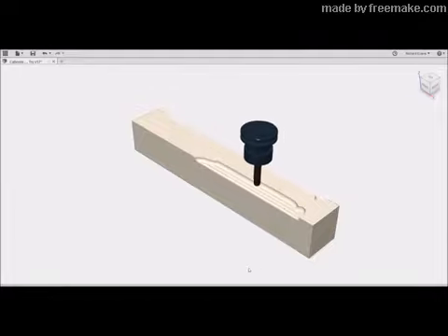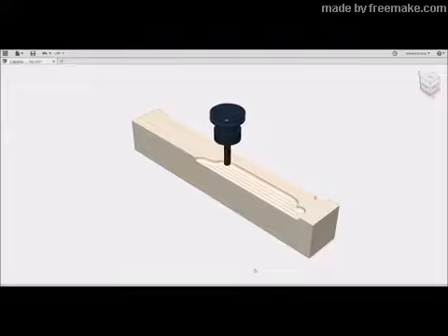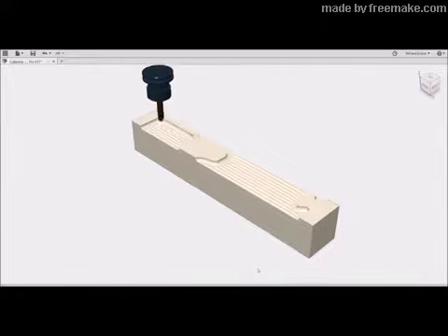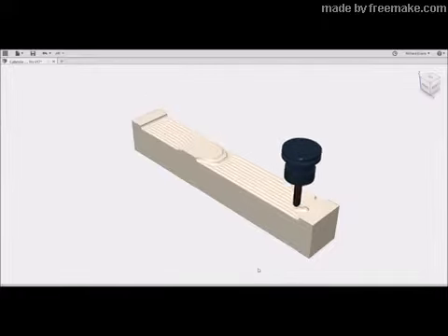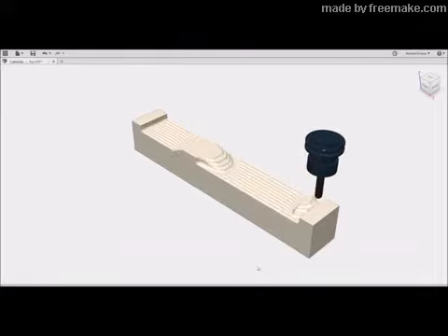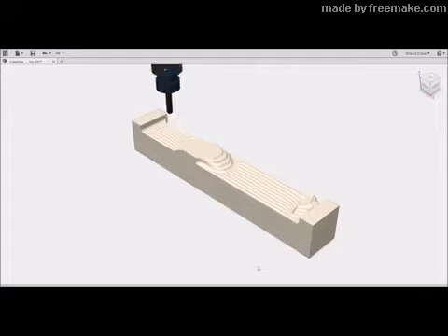The leg will be milled in 4 different tool paths, 1 for each side of the leg. The tool paths are designed to be cut in a specific order. The faces are named top, bottom, back, and front based on the initial position of the stock. The tool paths are run in that order: first top, second the bottom, third the back, fourth the front, with the stock manually rotated between the running of each path.